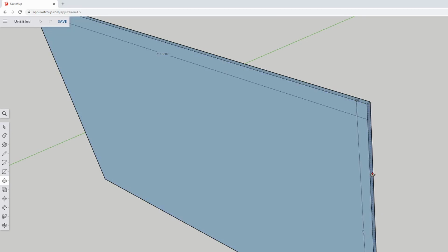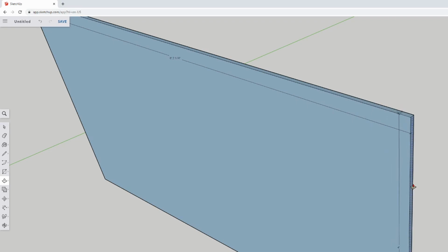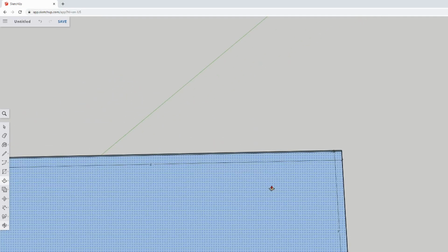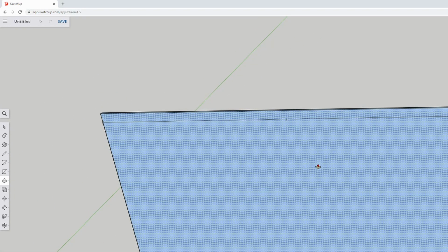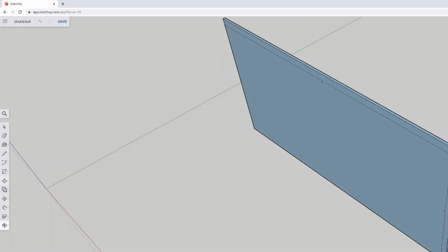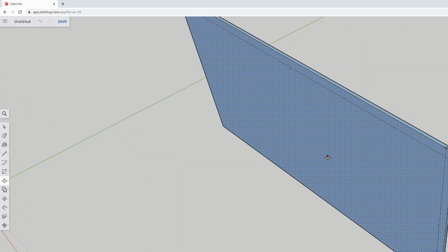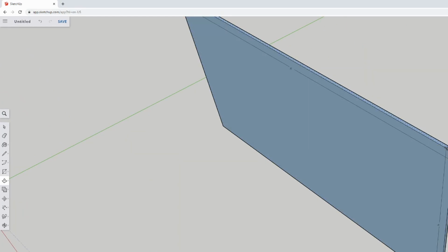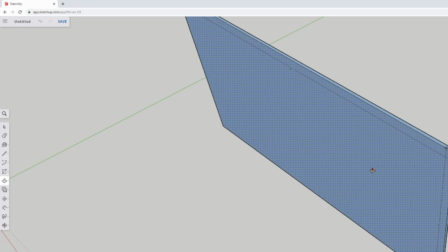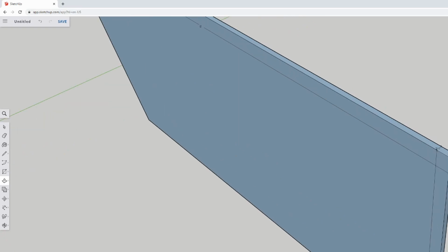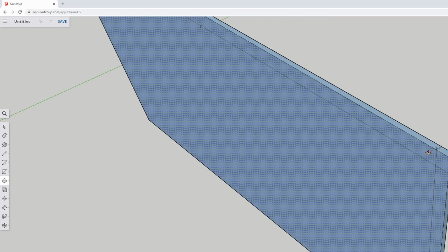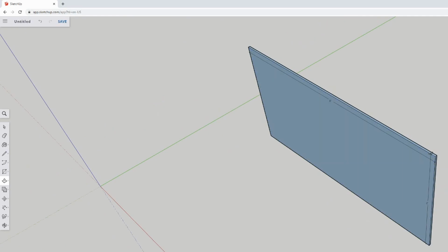So if we want to change the width now along this axis, we're going to drag it on this facing front and then drop it. So now we have a sheet of 8 foot by 4 foot with 3/4 inch depth piece of plywood. As I mentioned, a lot of the pieces that I work with start off in this fashion, right? So whatever dimensionally sized lumber you want to use, if you want to change this to 1/2 inch, 1/4 inch, it doesn't really matter. You just size it accordingly. So this way it now represents a full sheet.